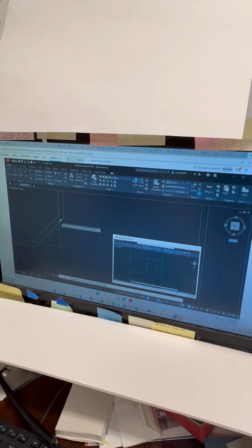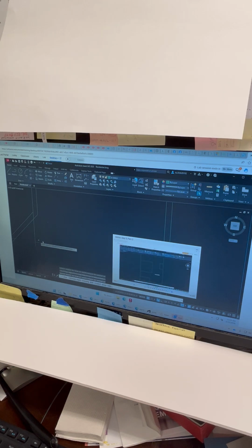I think I did something that's stuck on that. Can I back out of it? Yeah, you know what? Just start the command again. Just press the button again, chamfer. All right, now look at your prompt. Start the command. So type in D for distance.